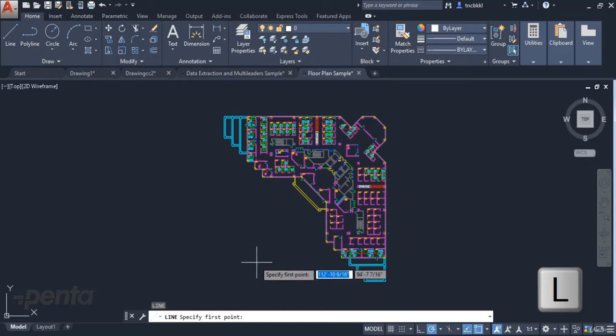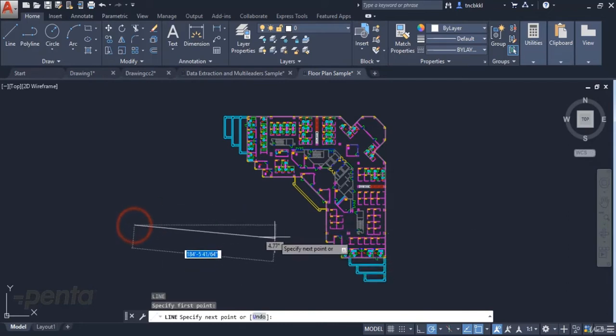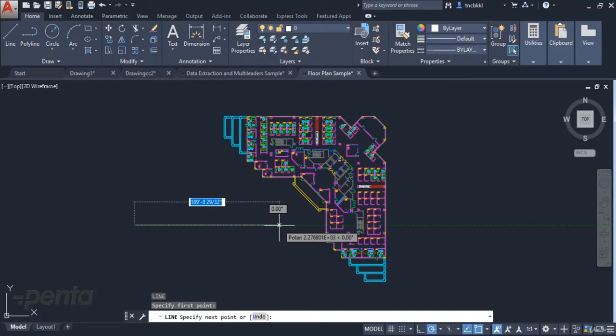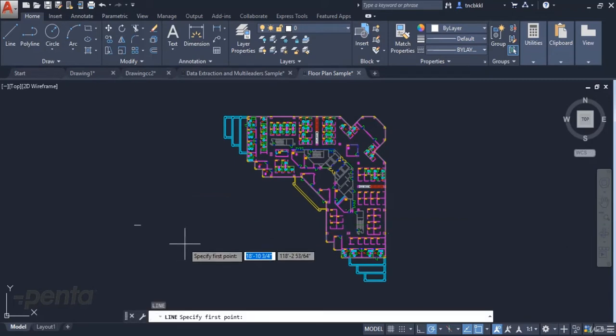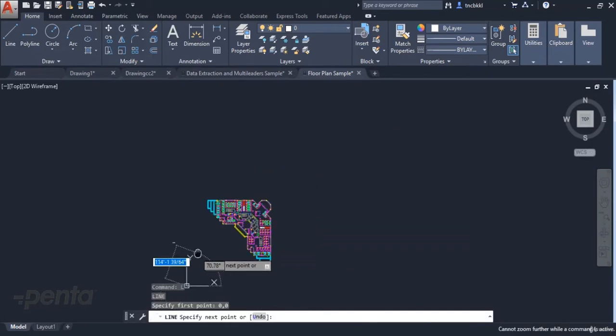When inputting data with our keyboards, what we need to be especially careful about is the difference between dots and commas. When we select the start point and want to set a length with decimals such as 100.2, I need to input the point value, and this is perceived as the length value. If we input a number with a comma at a random starting point in AutoCAD,